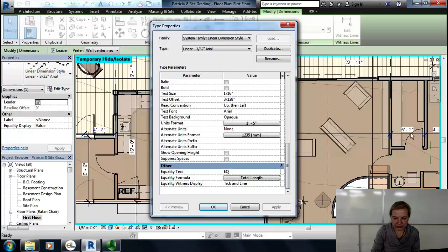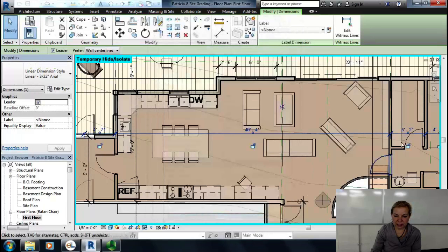But one thing I want to bring to your attention is this unique to Revit option of having the white background for your dimension. So if you have shading or material map showing, the dimension is basically showing on a white background so you can actually see it. And sometimes it's a good thing, sometimes it's not a good thing. Obviously, it's not going to show in black and white. But if you don't want it showing, you simply make it transparent and you say, okay, and now we don't have that white background. So you have to decide whether on your drawing this is called for or not.